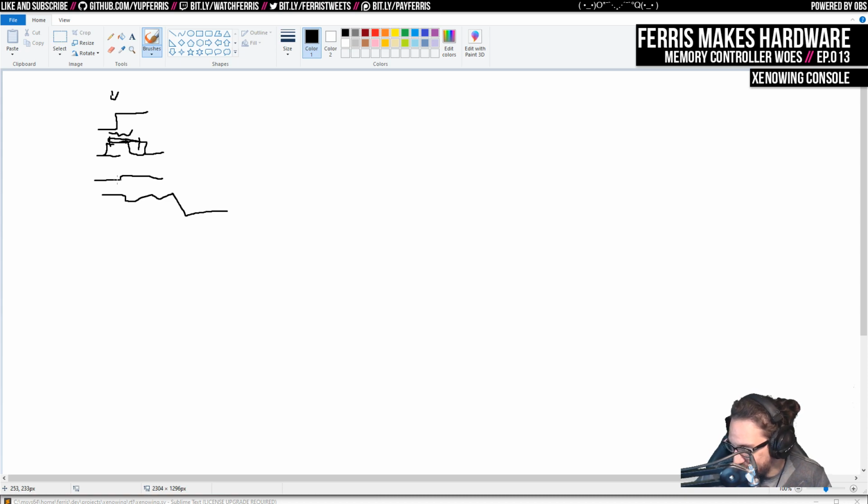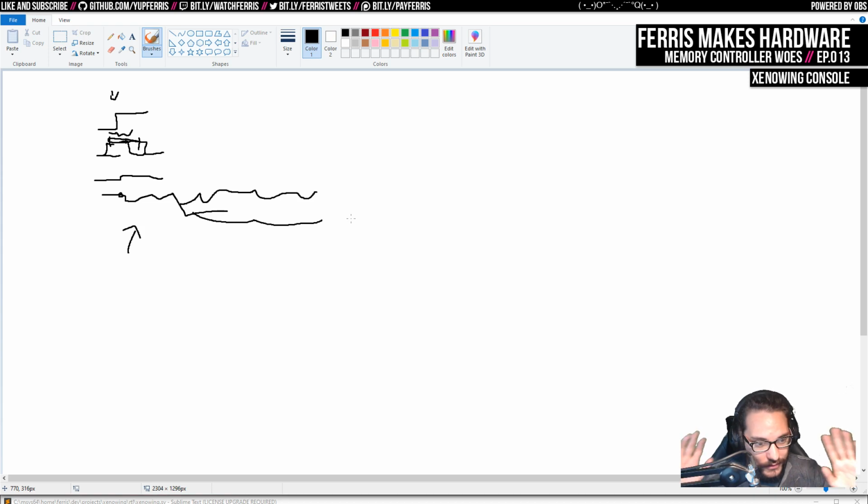I think it's a very interesting phenomenon. But the point is that if there's any signal that you want to synchronize to your clock, then once this metastability happens, let's say the output of our flip-flop started going like this. Maybe this feeds into another flip-flop, and then that starts going metastable, and then the entire state of your design is essentially compromised because of this one bad input.